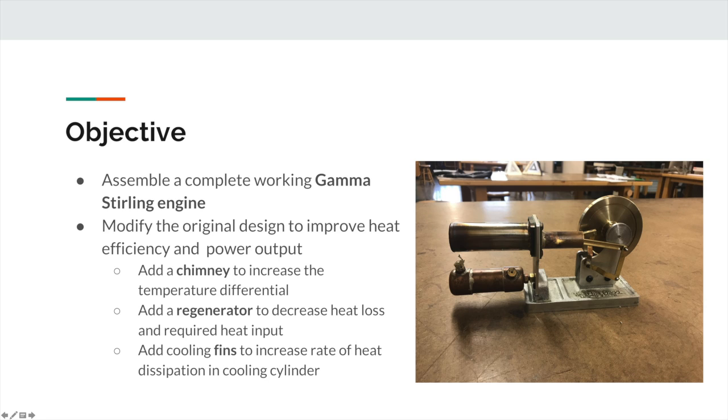The purpose of the regenerator is to recover the thermal energy input from the heating process during the cooling process. Finally, the cooling fins also serve to increase the temperature differential by increasing the rate of heat dissipation in the cool cylinder with a large surface area.